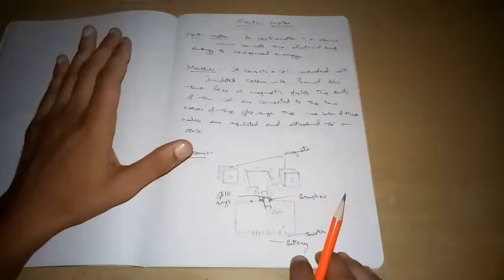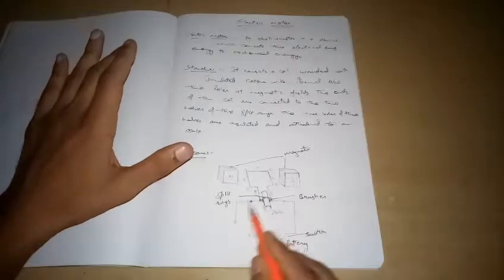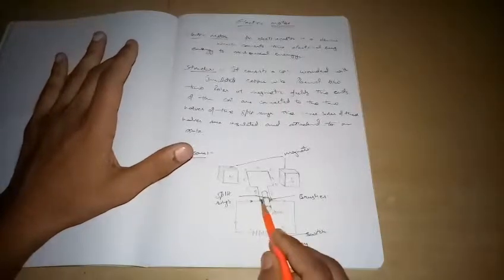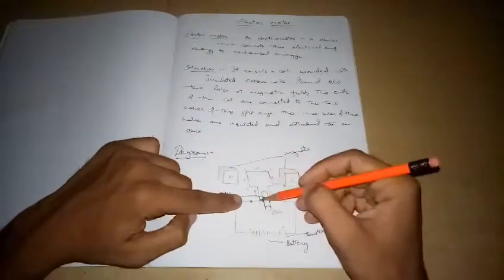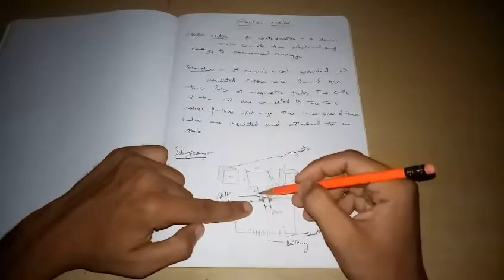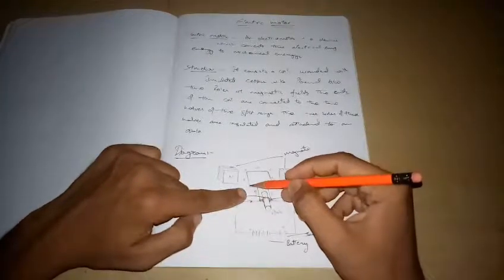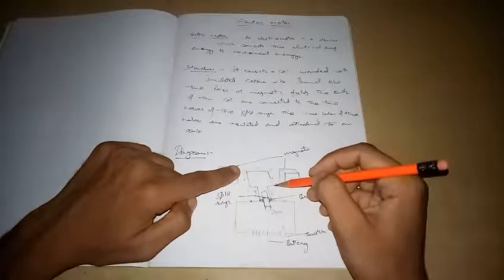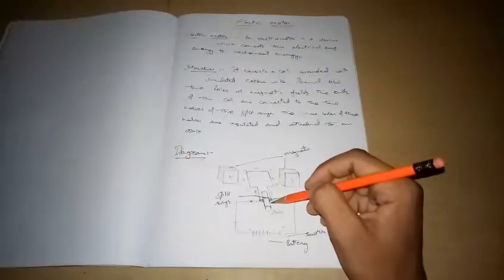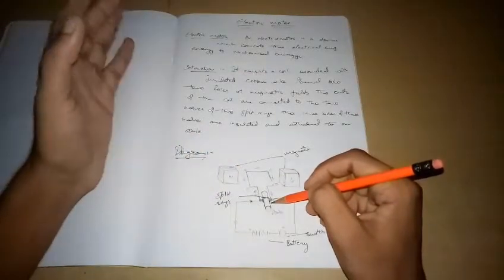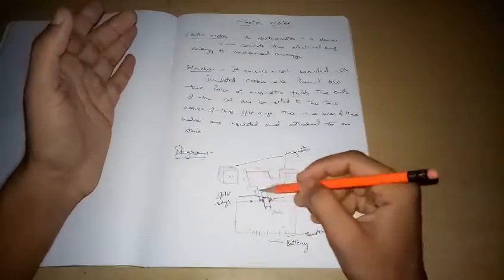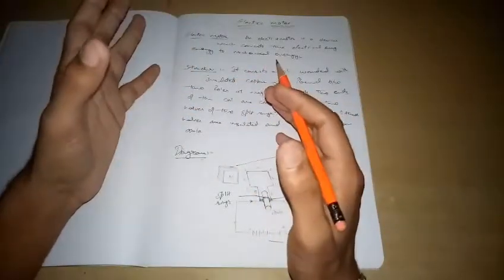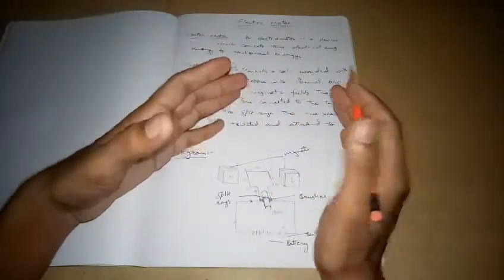After that, what about the working? When the electric current flows through the split ring, it flows through the coil. You can see the direction of the current through the arrows. It flows from A to B, B to C, C to D, and again moves through the split ring. Now, when the electric current passes through the coil, the coil acts as a magnet, and its movement is just like this.